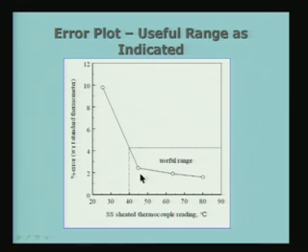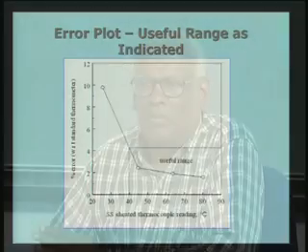I can use this relationship, this information, as a correction to correct the temperature obtained by using the thermocouple and make it agree with the standard thermocouple. So, this is real calibration, where I am trying to bring it in agreement with a standard reference thermocouple. The other one was utilitarian. This is a slightly different way of doing the same thing, but we are comparing a thermocouple of the same types for which the output is known. So, I would like to use the table for the purpose of determining the temperature.